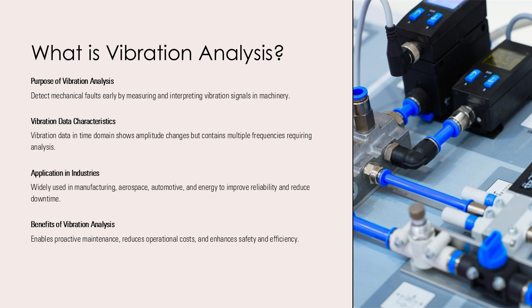The raw data collected is typically in the time domain, showing how vibration amplitude changes over time. However, analyzing this data directly can be challenging because complex machinery often produces vibrations composed of multiple frequencies. By studying these vibrations, engineers can identify patterns that indicate specific faults, such as high-frequency signals pointing to bearing defects or low-frequency signals suggesting imbalance.